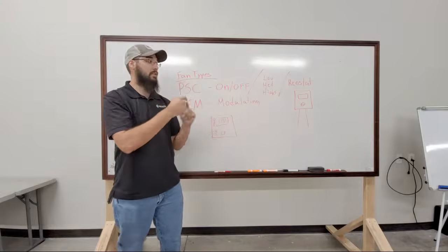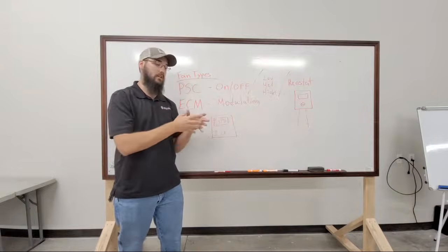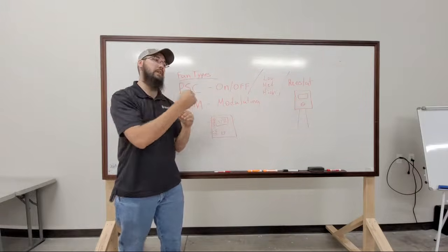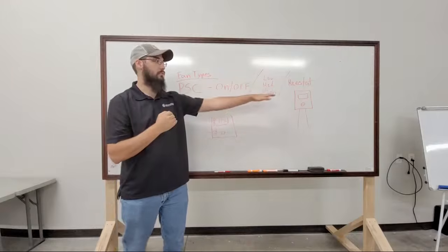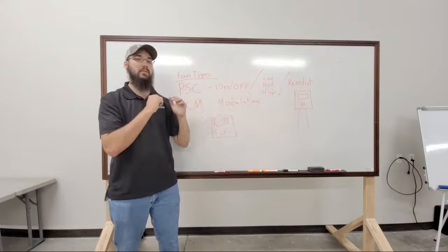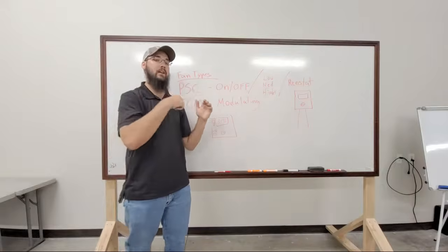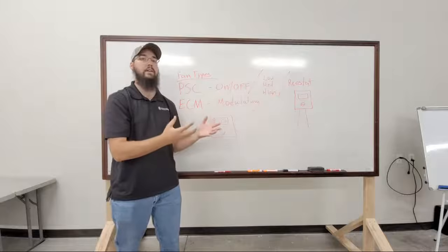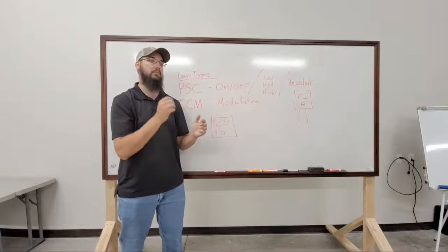If the motor is already spinning, it'll continue to run at that slow speed. But the moment it turns off, that motor speed controller, because it has too high of a resistance going through it, is not enough to allow the motor to actually turn back on, and the motor just sits there until it overheats and burns up. So you have to be careful of that.